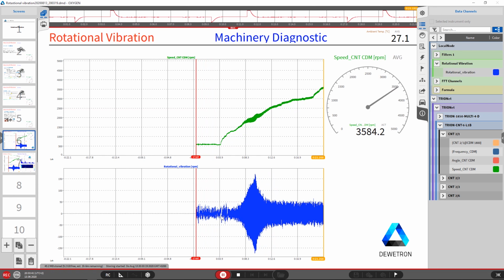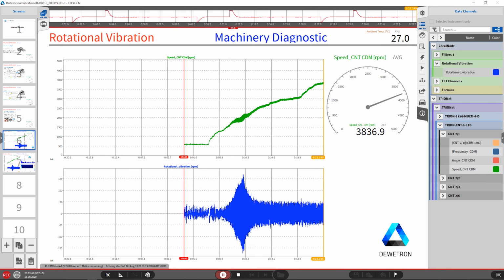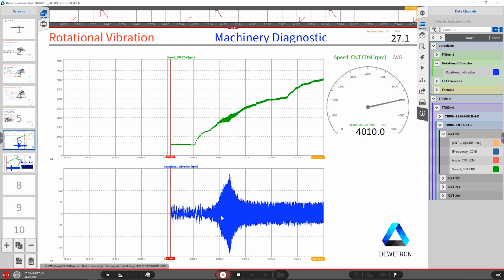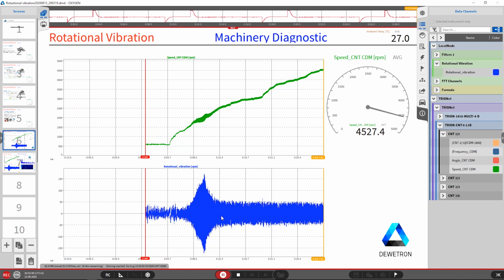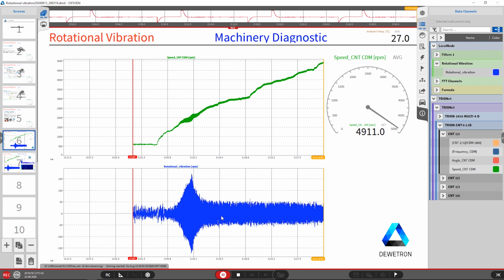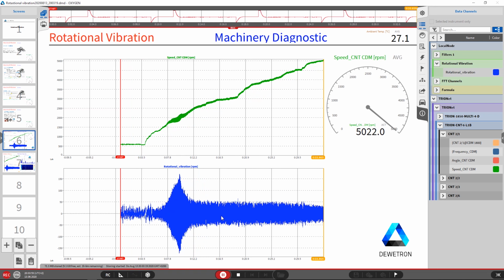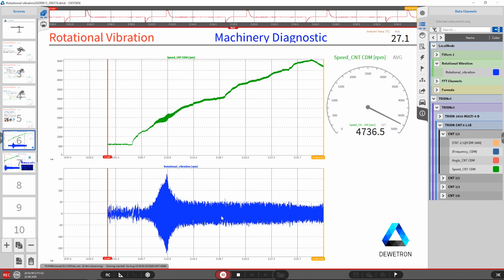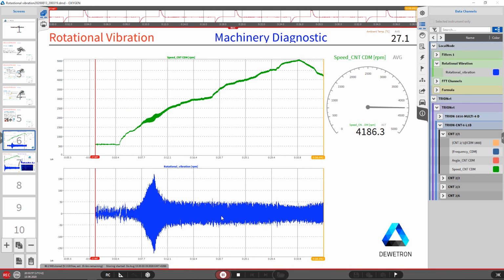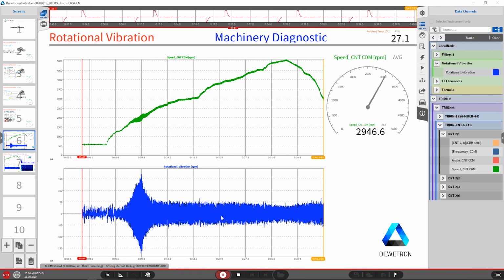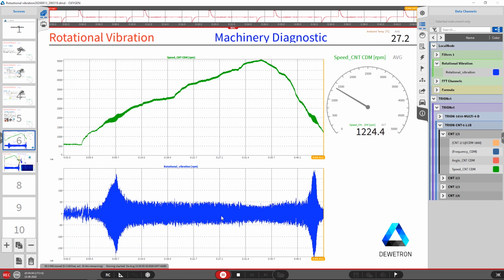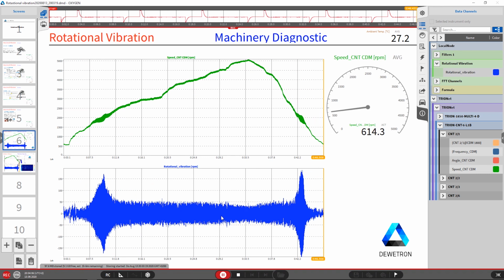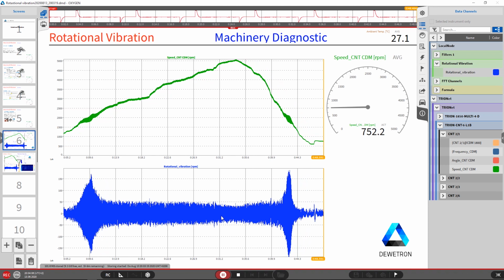We can see that at a certain RPM, it was 2000 RPM, we get a kind of border line, looks like noise, but we will in a minute do further investigation on this. And like you can imagine, we would see here then the rotational vibration. So let's do a quicker shot. It goes down, and I will stay here at 700 RPM.